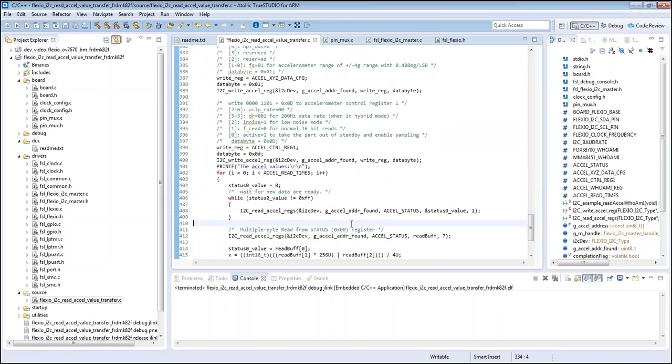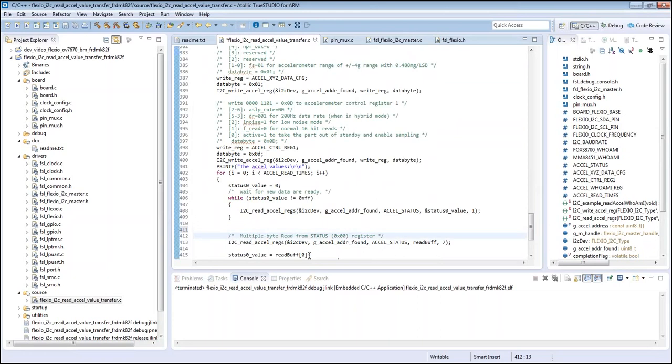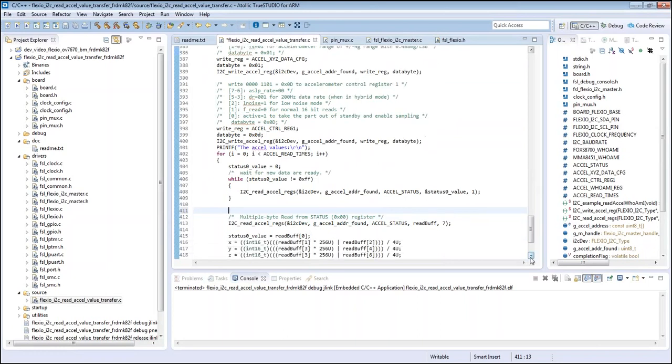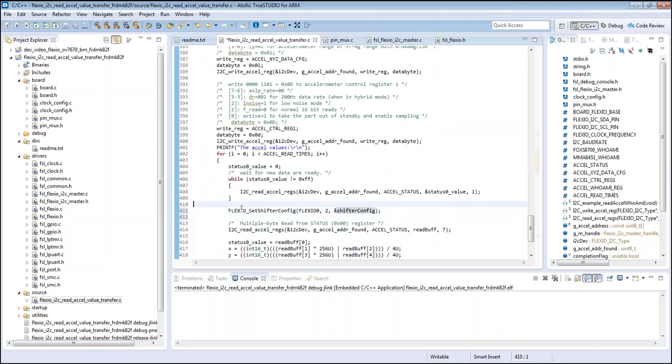We really only want to monitor once the I2C accelerometer is being read. We want to monitor only the relevant data. And so in order to do that, I'm going to move this code to initialize timer 2 and turn it on. I'm going to move it to right before we go off and read the accelerometer.